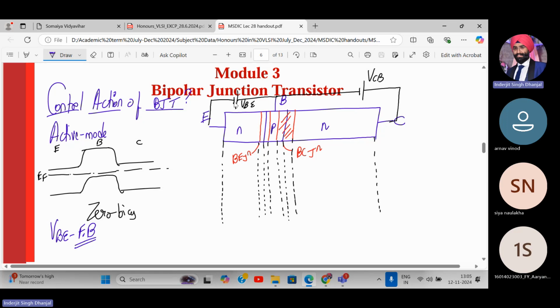But see here, the emitter terminal is getting a negative potential. So the electrons which are present over here will try to run away from this negative supply, because like charges repel, right? So these electrons will be pushed into the base region by forward bias. Do you remember what happens in forward bias? Now base emitter is forward bias, right? So we'll concentrate on this.